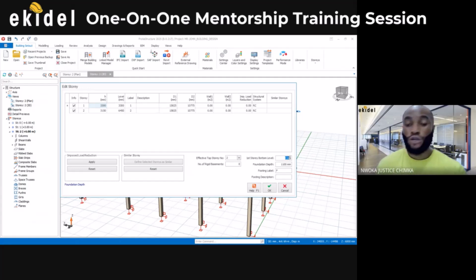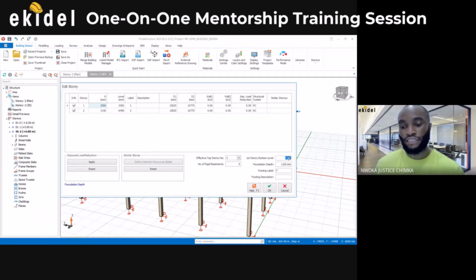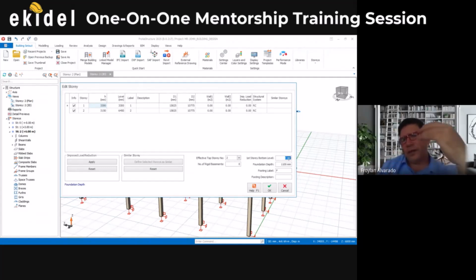So also here, you can choose to add that value here. You understand? 900. But in my own case here, in my country, for normal buildings we use 450 for private buildings, while for public structures we use 600. You understand? Although it all depends. For us it's because of the hurricane. Once a storm surge comes, it usually goes up about maybe 2.5 feet. So you don't want your buildings to be too low, no?